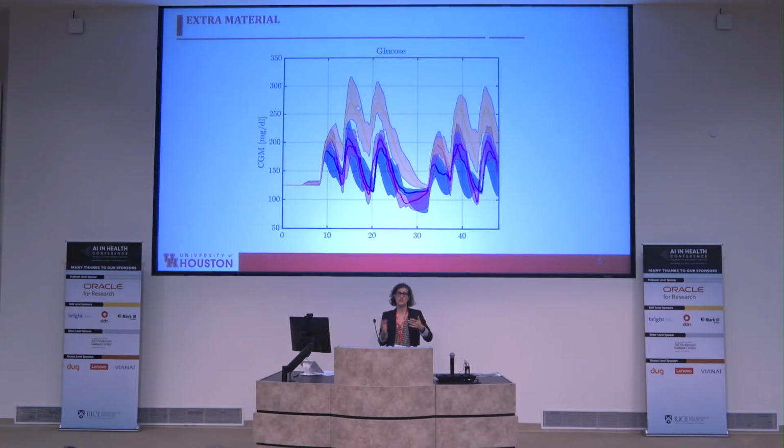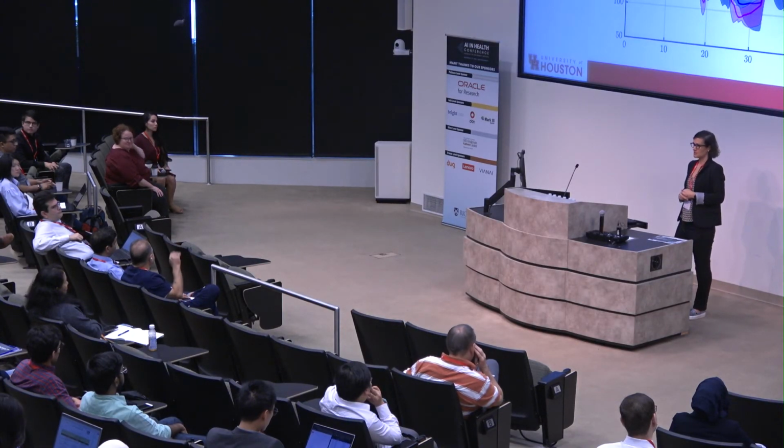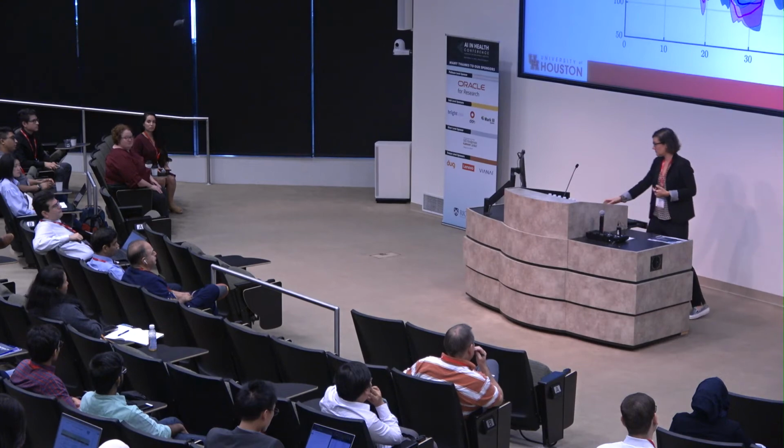This was just a simulation that we ran very quickly, where the yellow is a linear ARX model that we have trained on the same amount of data that we collected to train the LSTM, but with the limitation of a low complexity model, lower order, and worse performances. So in that sense, yes, you assume your dynamics is fixed. LSTM are quite complex in the control world to get it to run. But as we were mentioning earlier, we can find a way to update it at runtime. Yeah. I see.